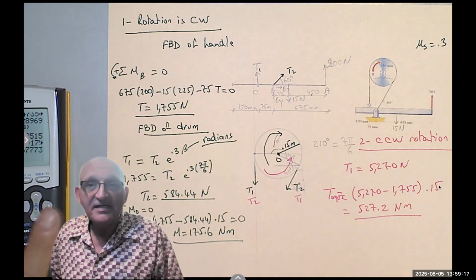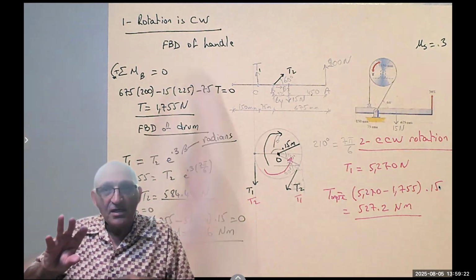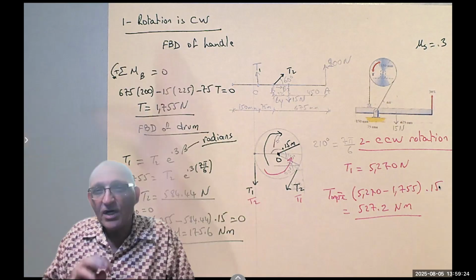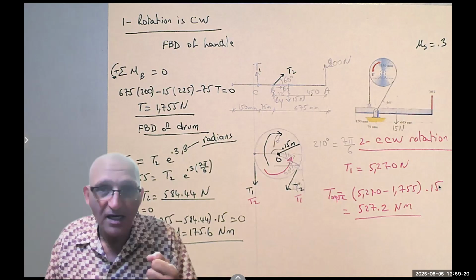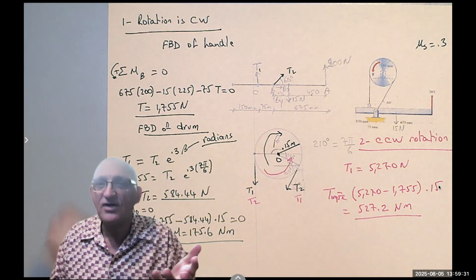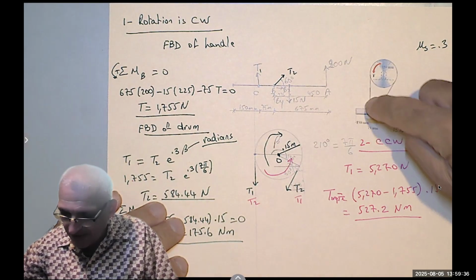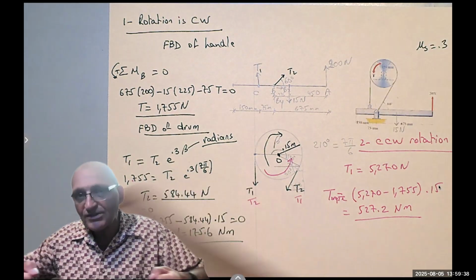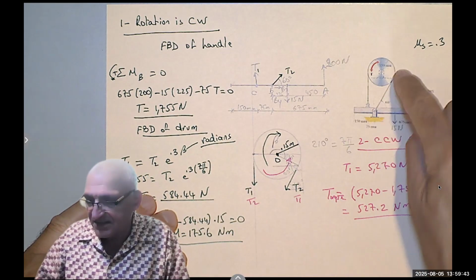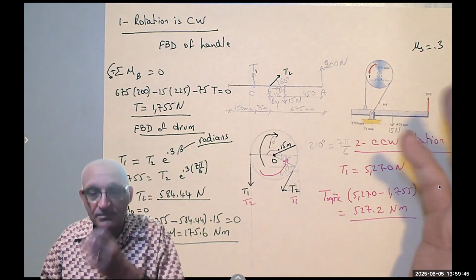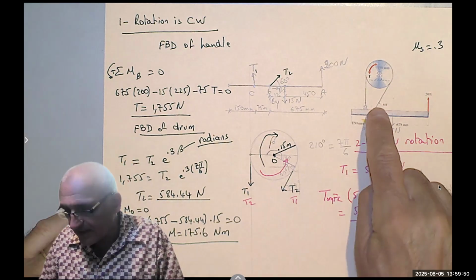So that's basically it for today. Please understand how, when it rotates clockwise or counterclockwise, which side is heavier or which side has a higher tension. It's so easy when you come to think about it. Think always that if you are rotating clockwise, you are pulling this piece, so it has more tension. It's stretched more. If you rotate counterclockwise, then definitely the inclined part would be the part that is carrying more load.